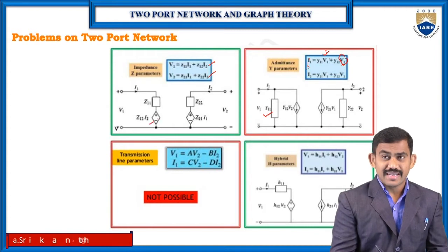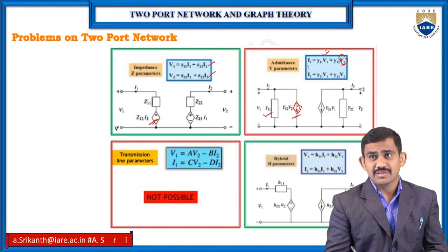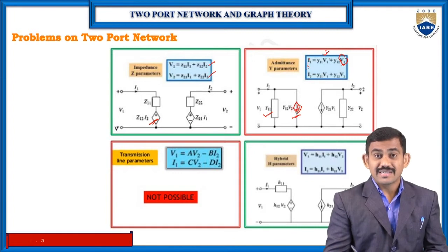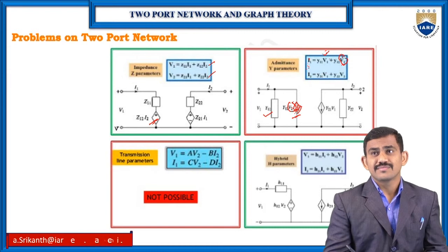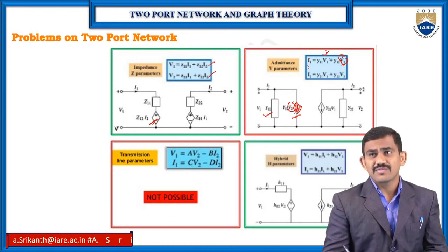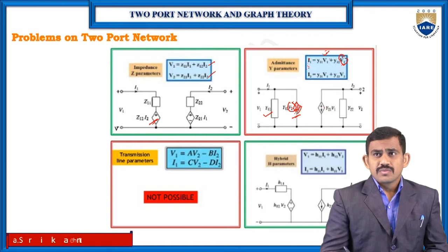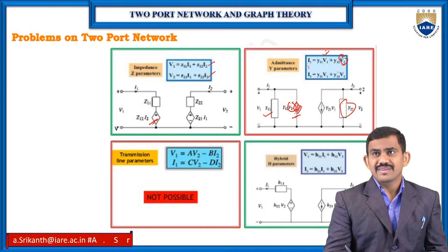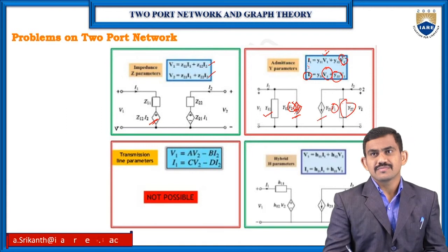So here we have the voltage source in the previous case, but here we have the current source, again a dependent source, depending upon your voltage V2 value. Same here, the second equation has Y22 admittance, and Y21 is depending upon your primary voltage.